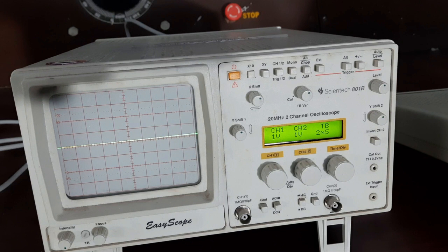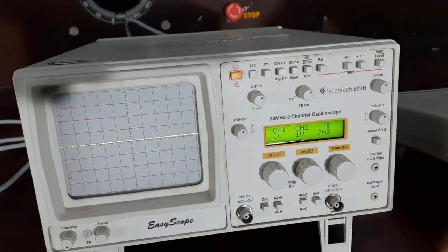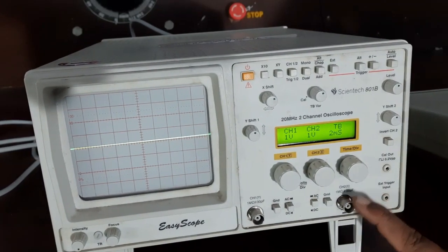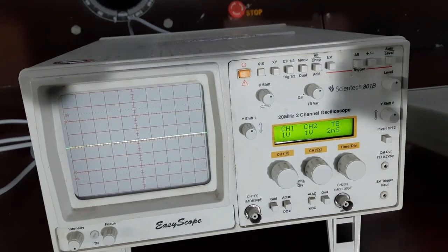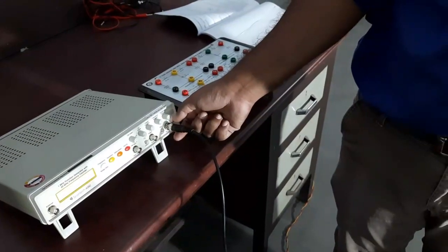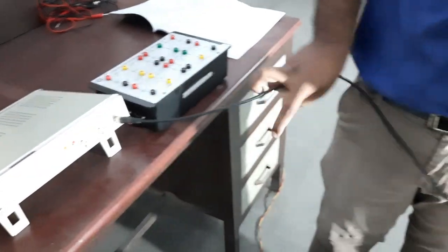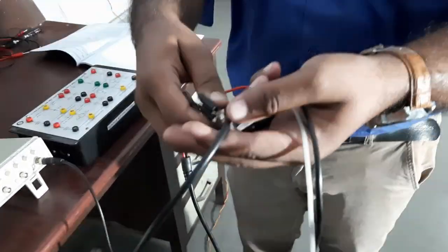That means, if you want to measure voltage and current, you put that voltage and current into a CRO, and the CRO will show exactly how the voltage and current look. Now you can see in this CRO there are 2 different channels, channel 1 and channel 2. We can display 2 different waves in the 2 channels, from this BNC connector or through this coaxial cable, which has 2 different ends, a black end and a red end.